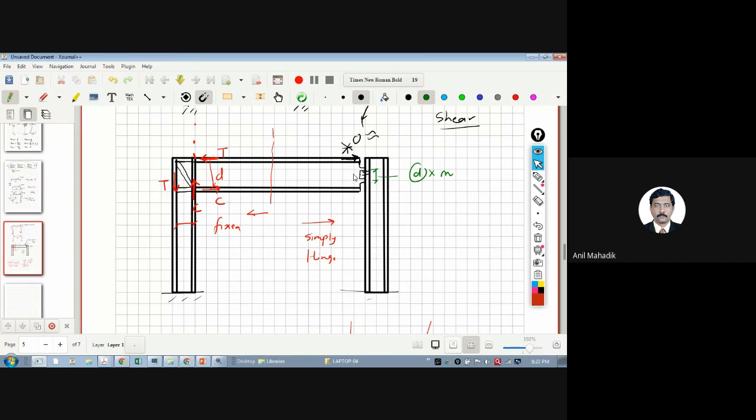Because whatever we say, it is not achieved in concrete structures. The assumptions of fixity and hinge connections in concrete are very difficult to achieve. And that's why we have more factors of safety in concrete structures. In steel structures, that is less. We are near to reality. So in this case, this D is very small, so it is near to a hinge structure. But still, I am saying it is near to the assumption. Whenever I say near to the assumption, still it is not exact.